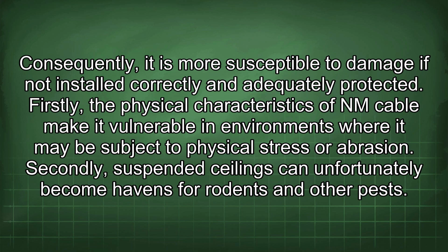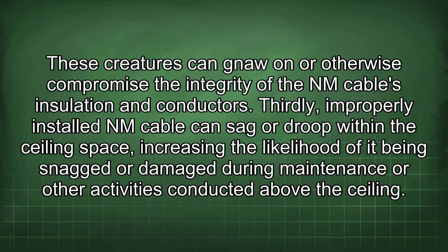Secondly, suspended ceilings can unfortunately become havens for rodents and other pests. These creatures can gnaw on or otherwise compromise the integrity of the NM cable's insulation and conductors. Thirdly, improperly installed NM cable can sag or droop within the ceiling space, increasing the likelihood of it being snagged or damaged during maintenance or other activities conducted above the ceiling.